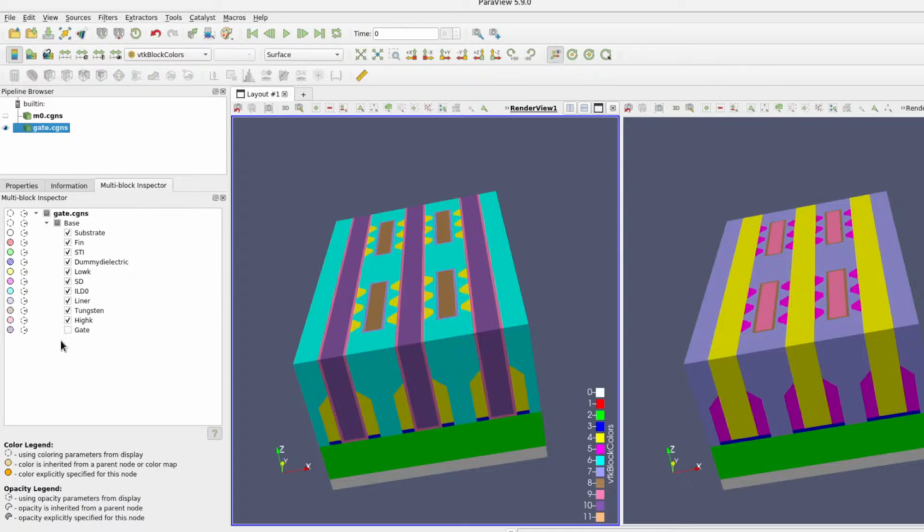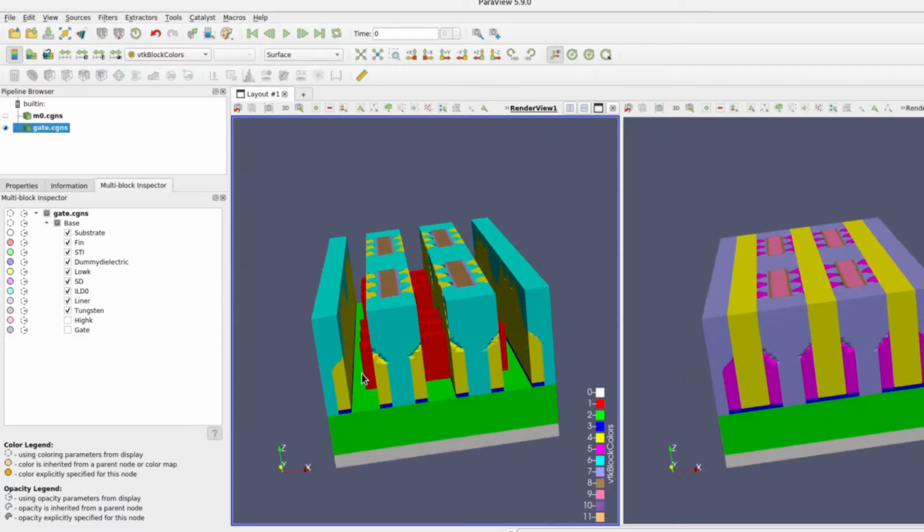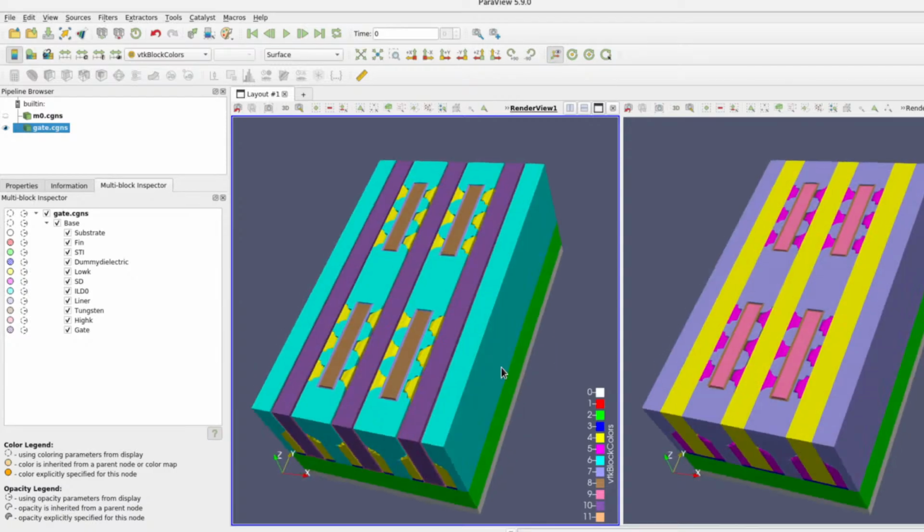This corresponds to the gate metal, and this is the high K dielectric. So first we remove this poly dummy gate. After that, we deposit high K using ALD, and also the gate is filled. Of course, this procedure is done with CMP. So now we have this pattern.